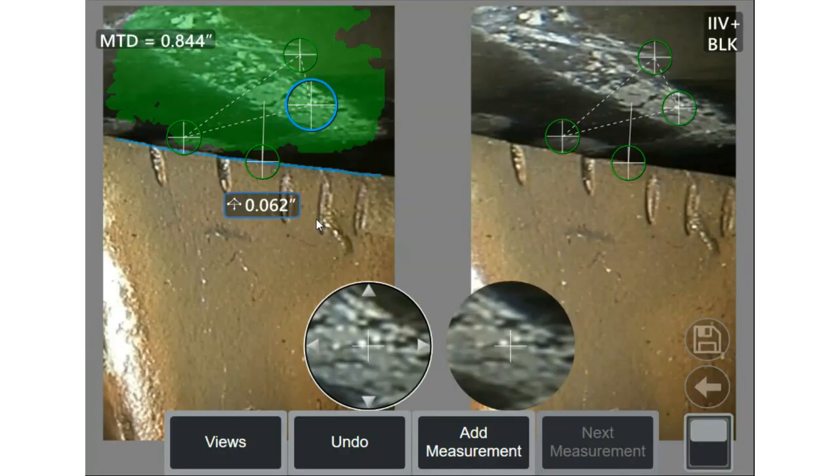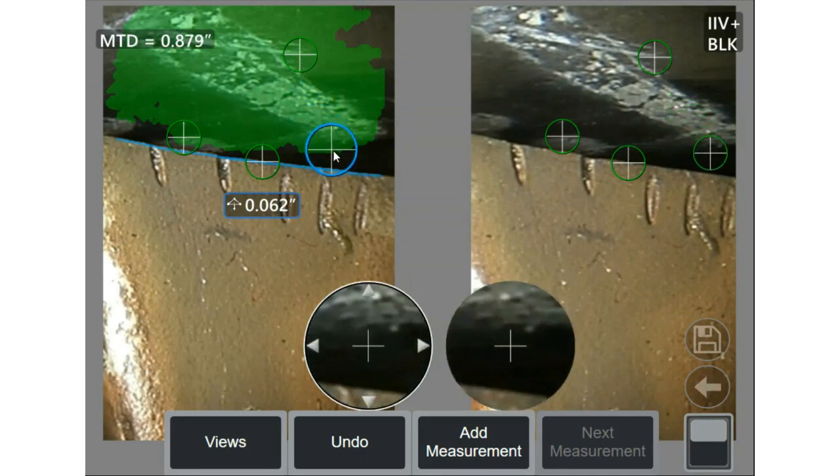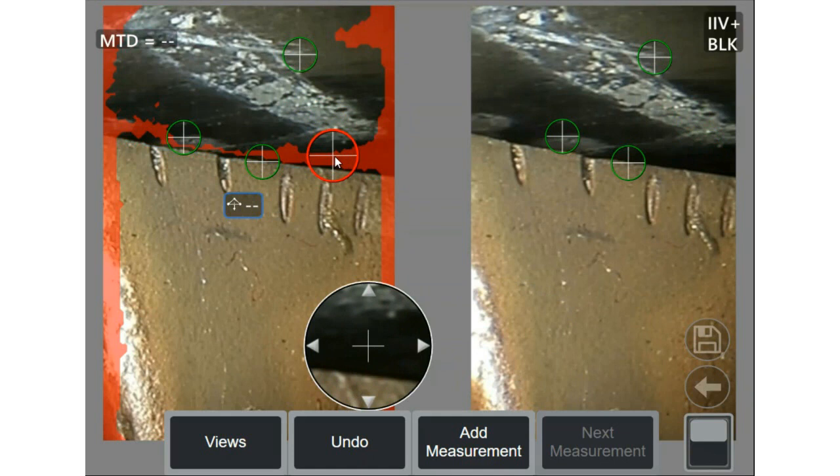And so you can now see that all of this data that's masked in green is actually on the shroud. Where I had the cursor before was up here. This red data is unmeasurable data. You want to avoid measuring around red data or unmeasurable data at all costs, just because that data is not necessarily stable or viable right around the fringe areas.